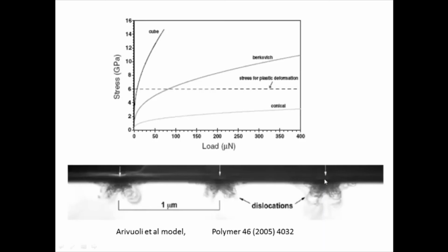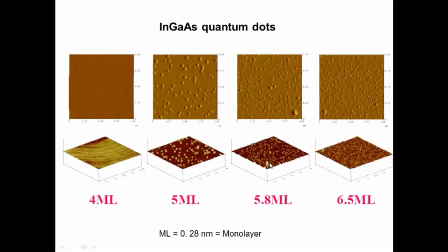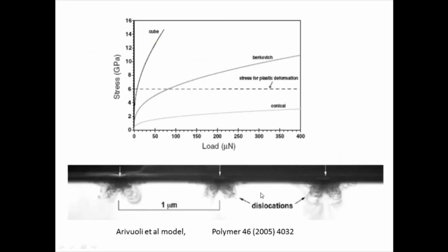Right? So when you indent, automatically dislocations are generated. You have to see that these dislocations do not interact. So this pitch, or the distance between adjacent indentations, you have to be very careful. If it is very near, they interact, and finally it will deteriorate the device characteristics. So with respect to time.